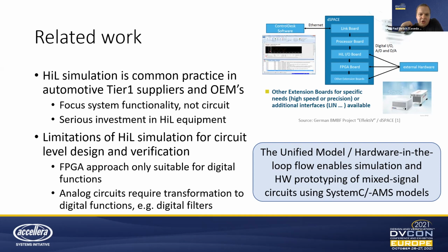In the upper right picture, you can see how such a dSPACE system is composed. You have a link board to the control computer, and a processor board where your application runs on an x86 machine, and then you have I/O boards to connect to the ECU which you're going to test.